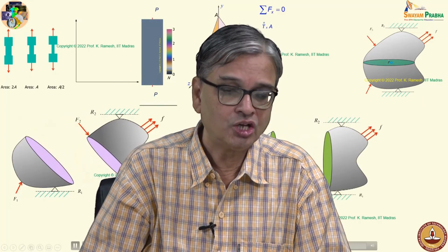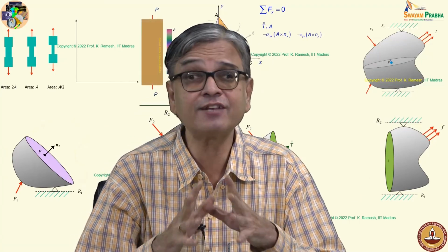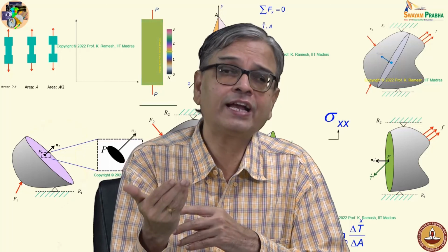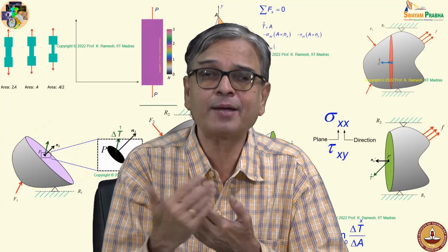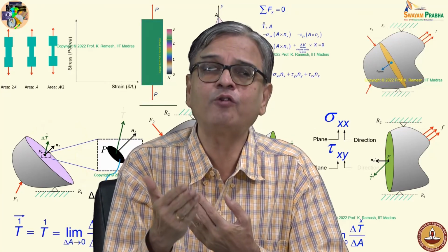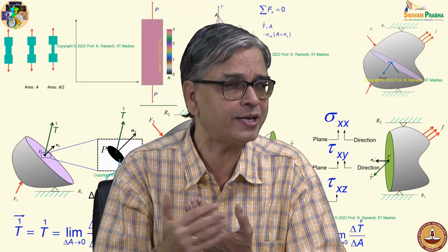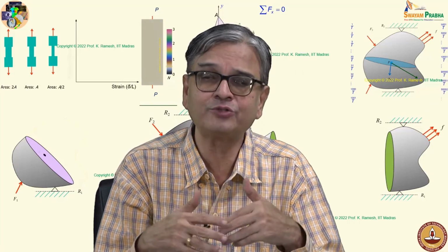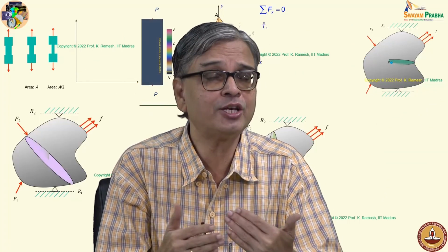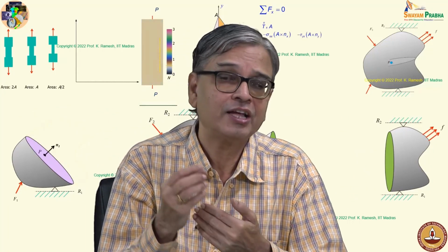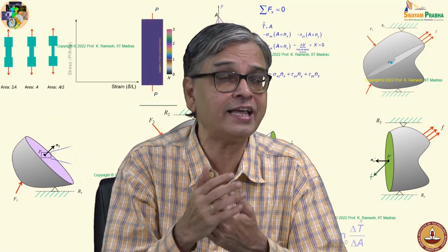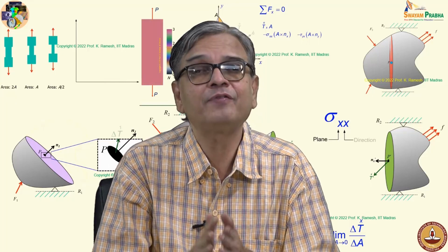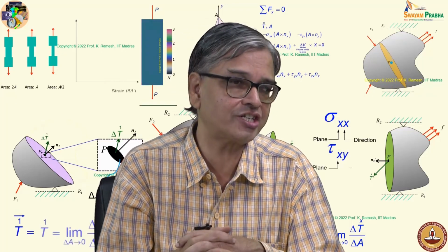Is the idea clear? So, in this lecture, we have developed the concept of state of stress at a point. We started with a simple understanding of P by A. Then we said, by looking at the experience of breaking a chalk, we have to find out what happens on arbitrary planes. Then we also found, in a generic situation, stress varies from point to point. You can't hold on to the cross section only as a basis to do it. We have to graduate to what happens at a point of interest. Then we developed a new mathematical entity where we defined, in a region very close to the point of interest, delta T by delta A, in the limit delta A tends to 0, remains finite. You are able to do that because it is an elastic continuum. And we define that quantity. This is also known as traction in advanced studies.